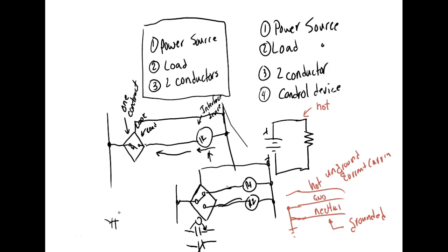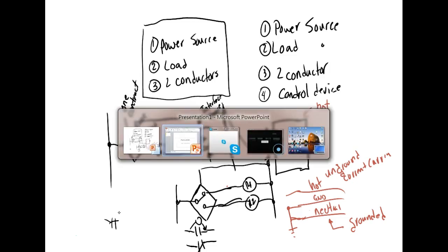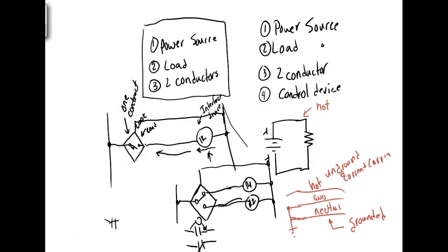Now these guys here, they'll also be standard. When you find one, well, the other one's gotta be the same. But what I was thinking is that you could do it before you power it up, and then I reneged on that, because both of them will be de-energized, and if both are de-energized, both of the normally closed will be closed, and both of the normally open will be open.